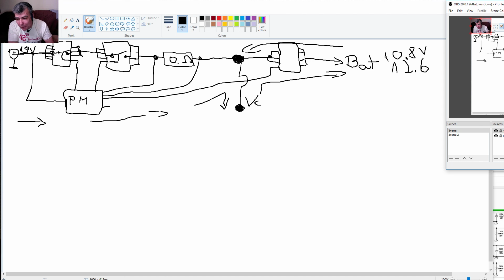If not, you have a big problem. It can be the processor, you know, it happened. You have the processor and the graphics on the same chip. If you play with the screen connector, you can burn the graphics in the processor. And you see the laptop is coming on, but it's displaying nothing. That can happen. You can try a different processor.